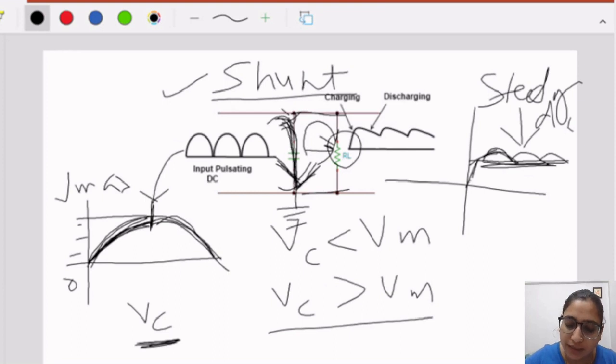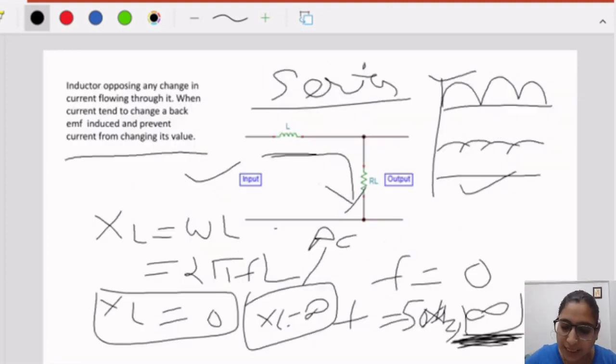It is providing the shunt path for AC components, so AC components are gone, and when DC components come it will behave as an open circuit. So the voltage is transferred to the RL, so in the capacitive filter voltage is the output factor. Similarly, in the L or inductive filter, current is the output factor. So in this class, we clearly considered two filters.